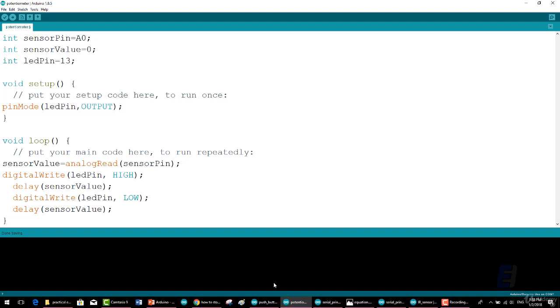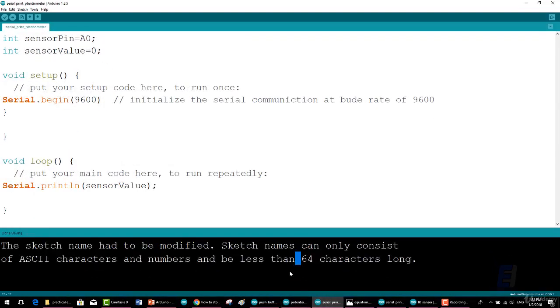You can test this using a multimeter, connecting the ends to the middle pin and an outer pin. Set the multimeter to read resistance and rotate the knob. If the resistance changes smoothly, the pot is working. If the resistance is erratic, you need a new potentiometer.